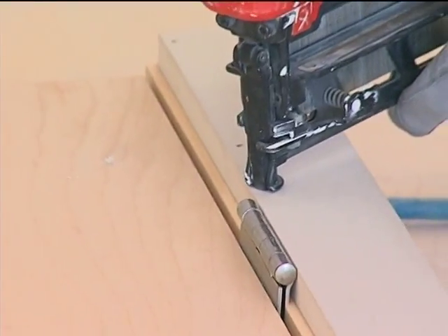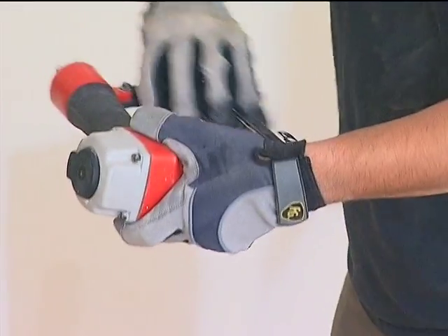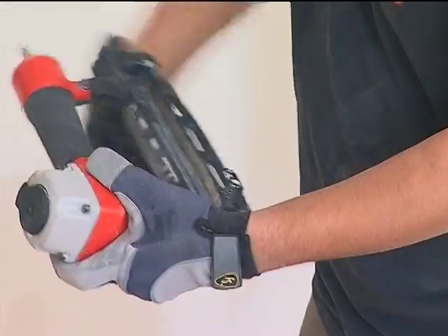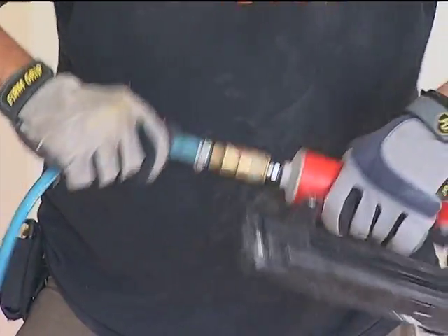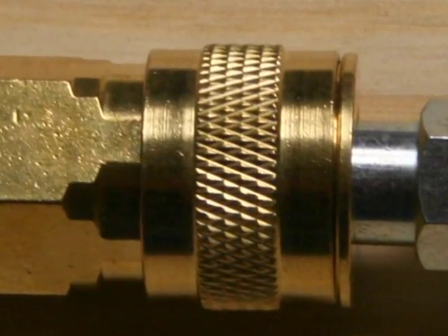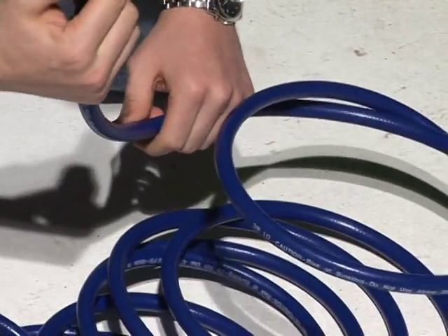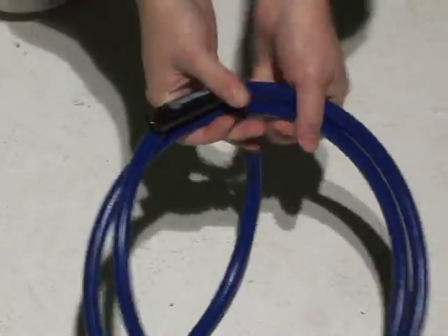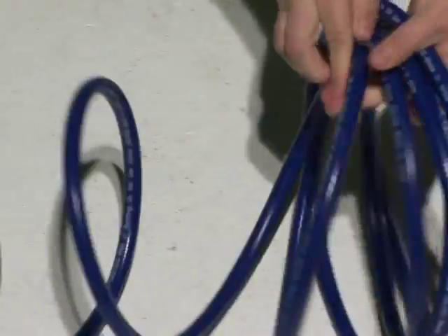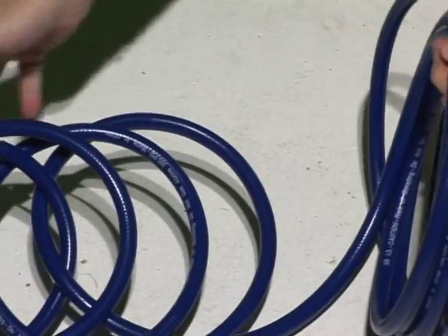A positive locking safety clip or retainer must be installed to prevent attachments from being ejected during operation. Double check to make sure the safety clip is working properly. Always check to ensure the tools are securely fastened to the air hose. Use wire clips where required. Precautions should be taken with the air hose to keep it from being damaged or to prevent someone from tripping over the hose. Never drag a hose across a walkway.